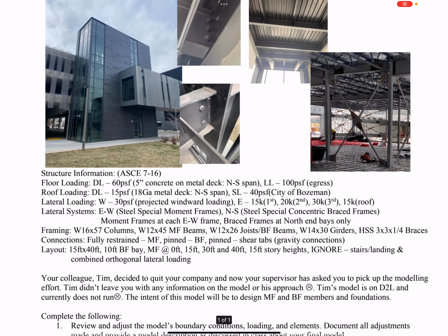Lateral loading, well, we have a wind load, okay? Strength level, 30 pounds per square foot. This is projected on the windward side of this stair tower. Ignore the parking garage, right? I'm simplifying this. When you go out there, I give you a VA file. It's out there, and you'll see I just modeled this, okay?